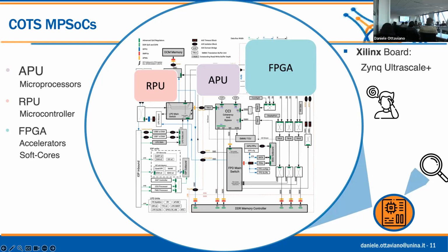Imagine them like a microprocessor, so they don't have support for virtual memory, they don't have an MMU, but they have an MPU, memory protection unit. So they don't have the translation from virtual to physical in hardware, but they just protect the memory through tables.